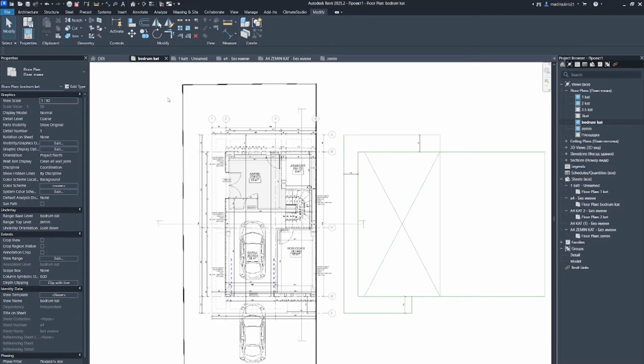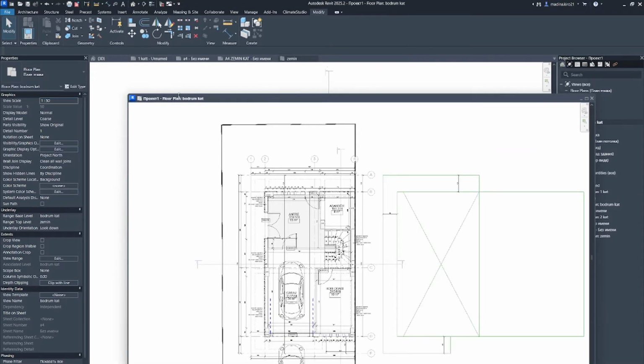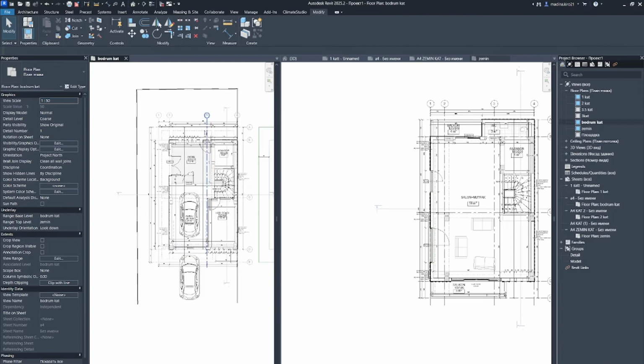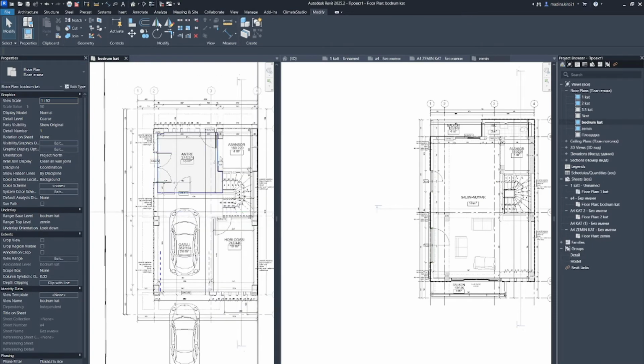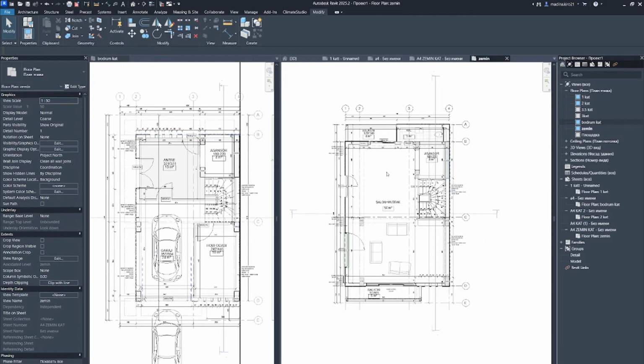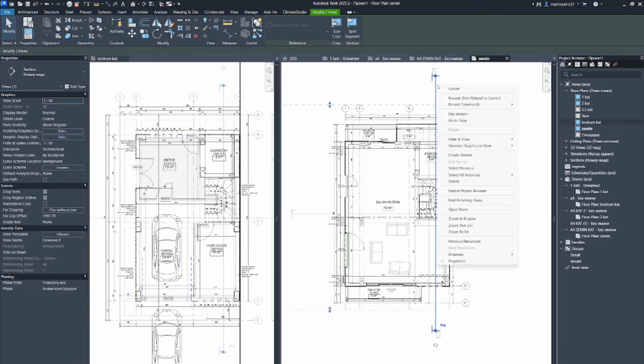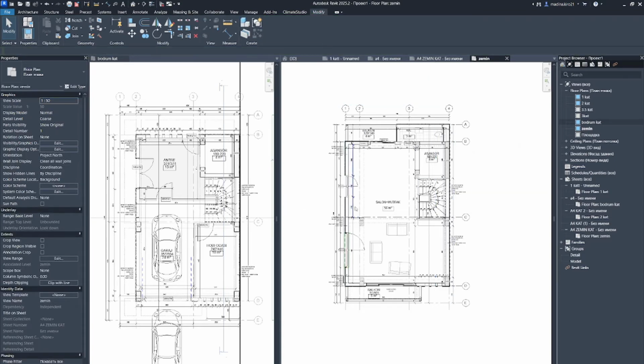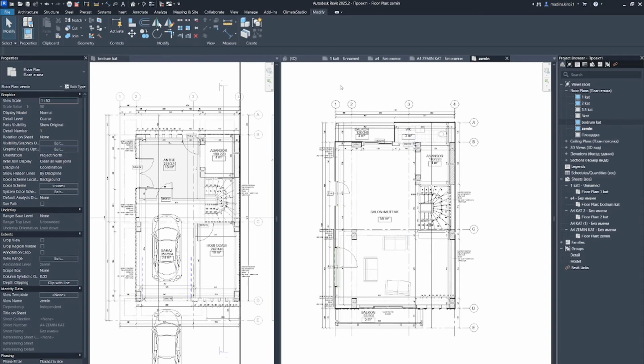So let's continue. I want to take this view as a reference to look at when I need it. So what I'm going to do is take this view from here and then come to the left side. As you can see, our screen is divided into two projects now. Now I will look at this one and then change something here. These sections, I don't want to see them now, so I will just hide them as a category because I have two sections and I hide them automatically. If there were more, then all of them would be hidden already.